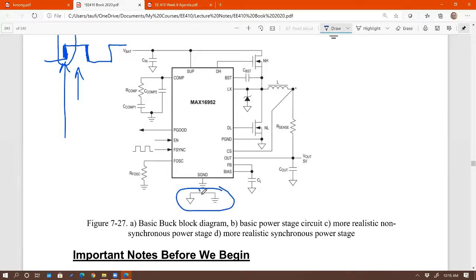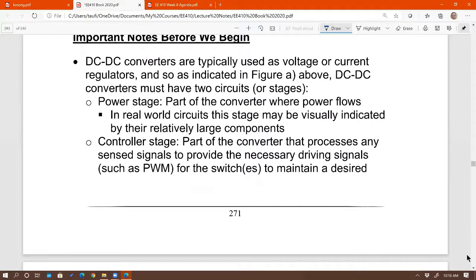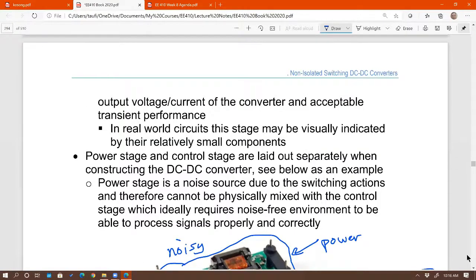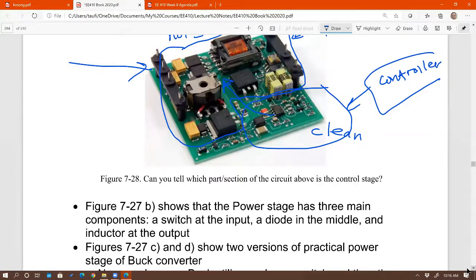Usually it's using a small, tiny resistance, right? As an attempt to isolate controller grounds, we call it signal grounds, from power ground. You can see all of the triangles, those are power ground. Right? Ground bounce is gnarly. Oh yeah, it is. They're very noisy. So you don't want to mix them up with signal ground.